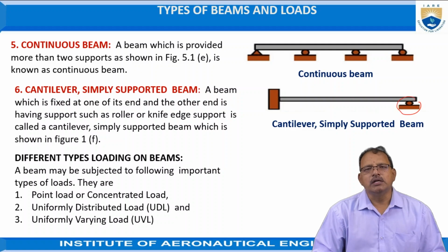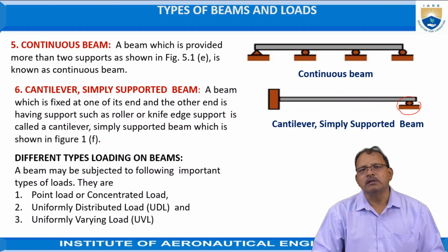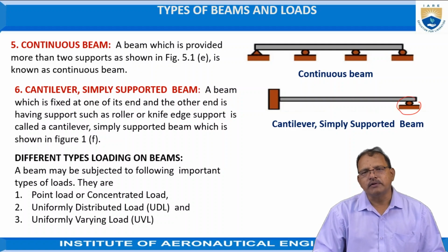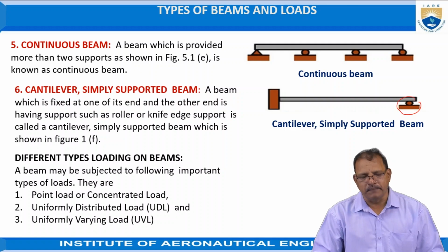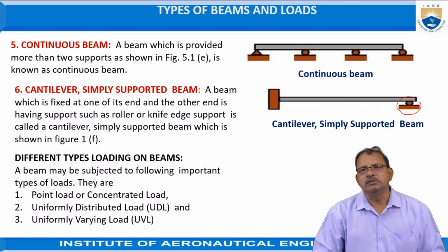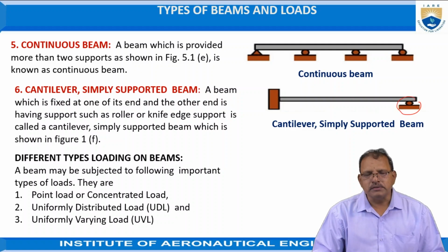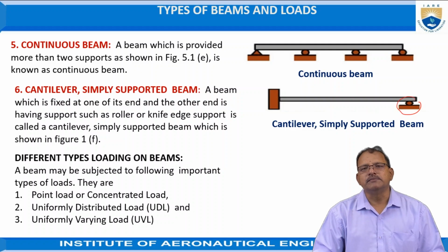Here, shear force is already defined. It is the unbalanced vertical force acting on the beam, or it is treated as the algebraic sum of the vertical loads acting perpendicular to the beam, considering the left-hand or right-hand portion of the beam. These vertical loads are classified as: one, a point load, also called a concentrated load; the second, a uniformly distributed load, simply written as UDL.